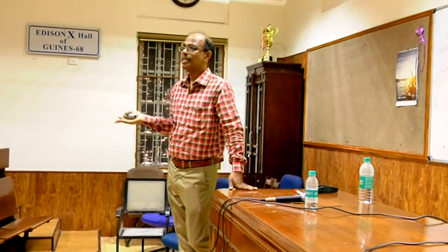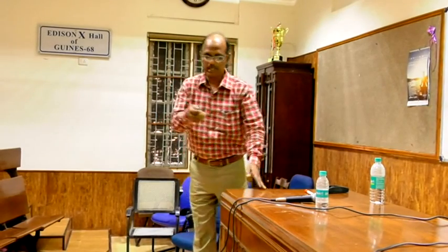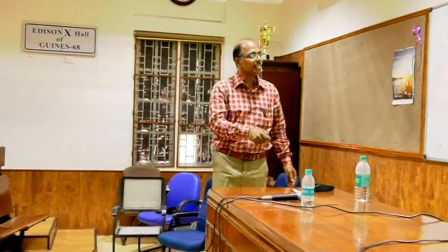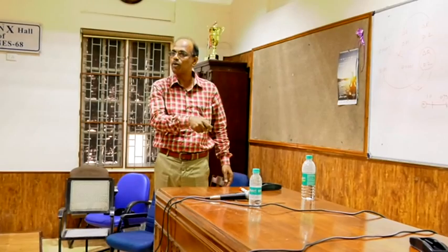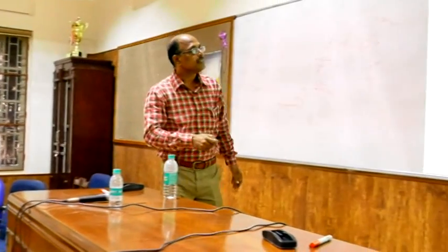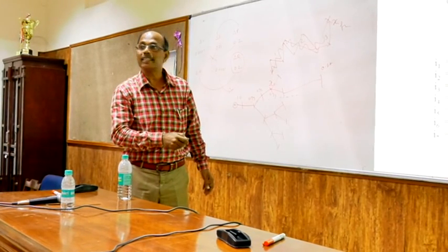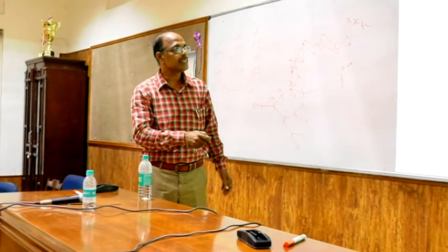At the beginning, voltages are not known. That is the problem. The problem is to find voltages. So you can assume the initial voltage as the substation voltage, 1 plus j0. That is assumed for all bus voltages. You can evaluate J1. Once J1 is calculated, then J1, J2, up to J7 are known. Once these load currents are known, then the current through this branch 7, this feeder 7, is nothing but the current at the load point 7. The current J7 is the feeder current.